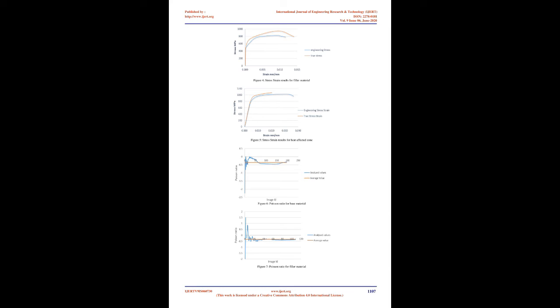Poisson's ratio. Poisson's ratio is the ratio of transverse contraction strain to longitudinal extension strain in the direction of stretching force. Tensile deformation is considered positive and compressive deformation is considered negative. The definition of Poisson's ratio contains a minus sign so that normal materials have a positive ratio. Poisson's ratio equals minus transverse over longitudinal strain. Poisson's ratio for all studied samples are determined and the negative sign from the equation above is neglected in calculation. The results for Poisson ratios are shown in a graphical way from Figure 6 to Figure 8.